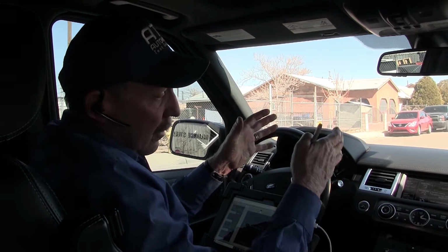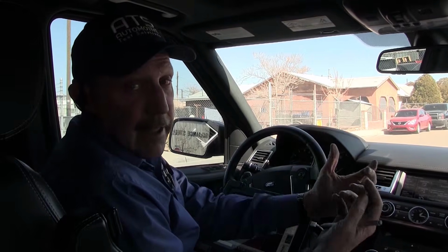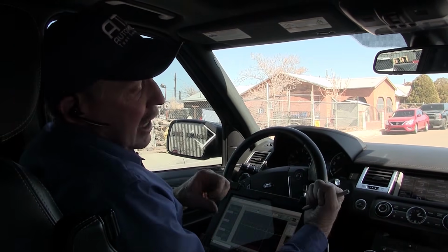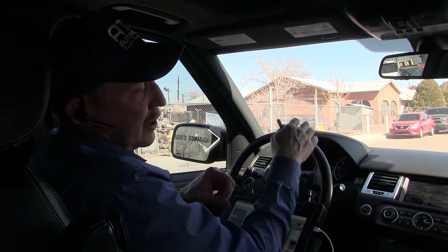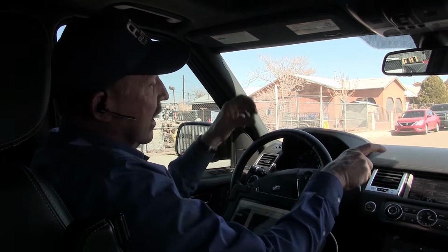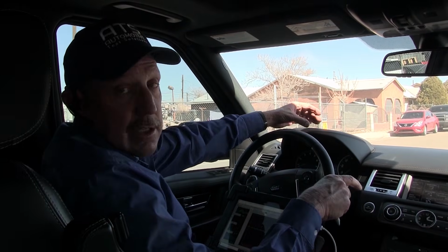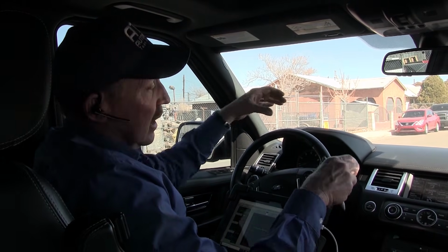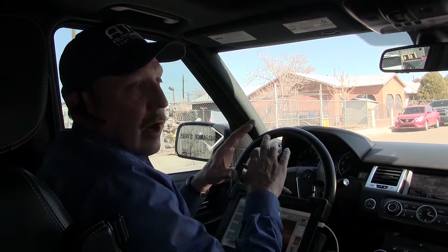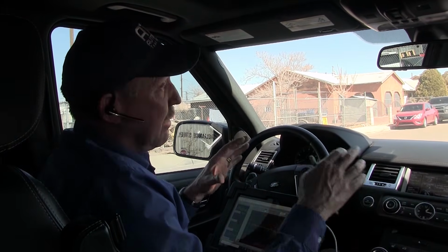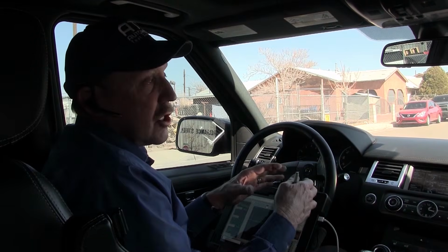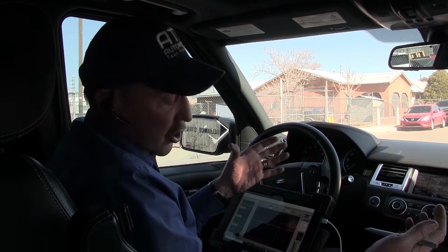In other words, when I pulse one pump, they go into a common rail. First off, it's one common rail. But I build pressure, and one pump is building for the 2 outside, 1 and 7, and this is the 2 inside cylinders, 4 and 6. And the other pump is the 2 outside and the 2 inside, so it wouldn't give me a bank fuel trim problem, but I'm having a bank problem on one more than two, but both banks have a control issue.